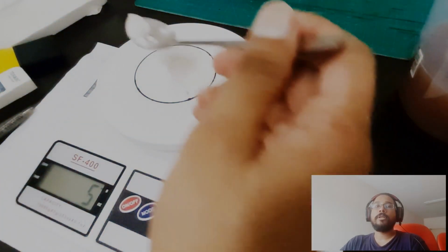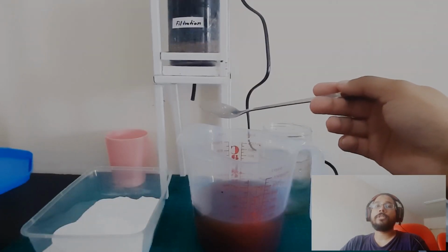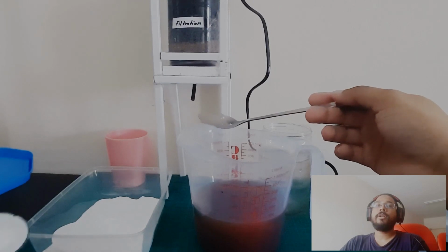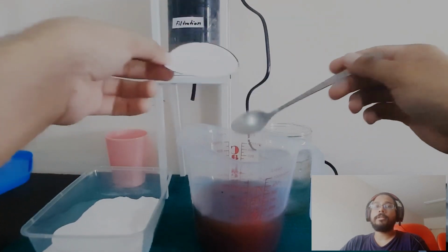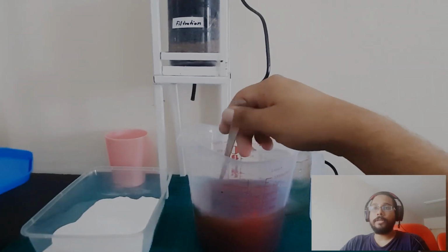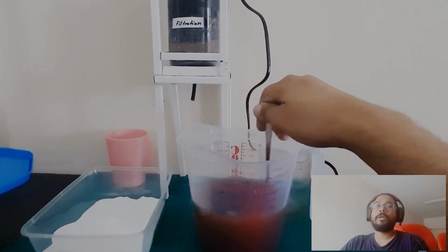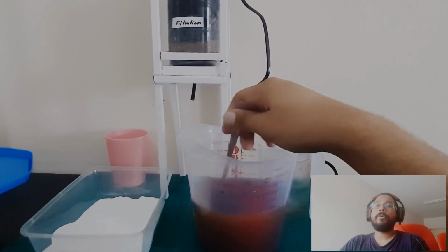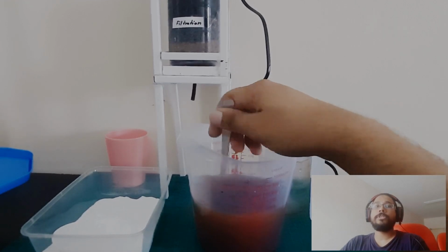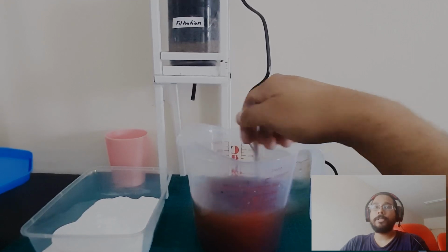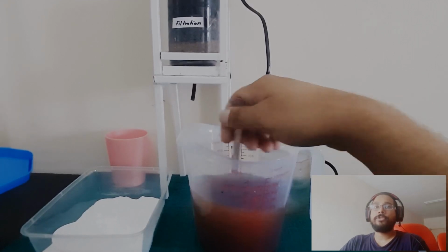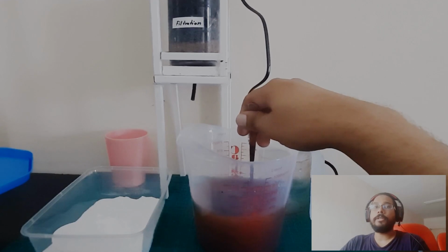Due to this, the increased alum dosage concentration in the solution may have contributed to increased turbidity and electrical conductivity of the treated water sample. To correct this in a redesign, a more accurate scale can be used to measure precise amounts of alum up to 0.025 grams per liter, and further testing should be done on limits within that range.